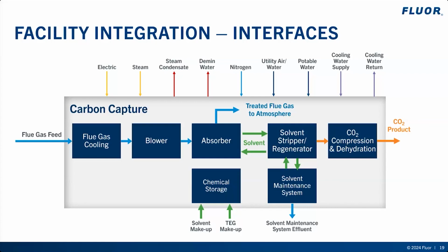Power, steam, and cooling utility requirements are significant and will likely require either expansion of existing utility systems or dedicated new utility infrastructure. The approach to utility design can have a significant impact on carbon capture plant scope of facilities, project capital costs, and plot plan constraints.